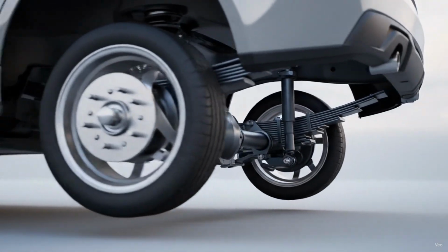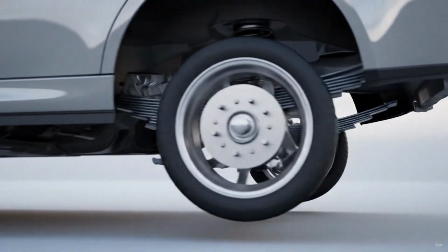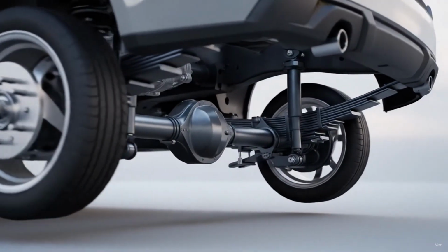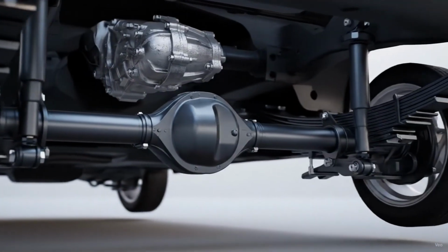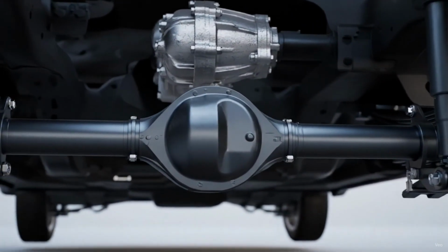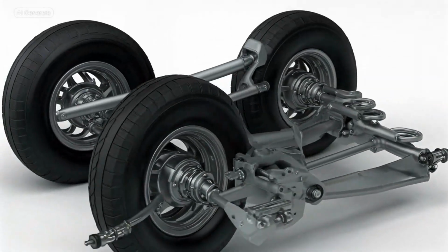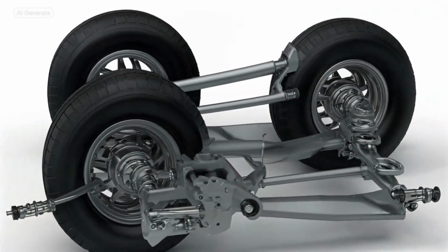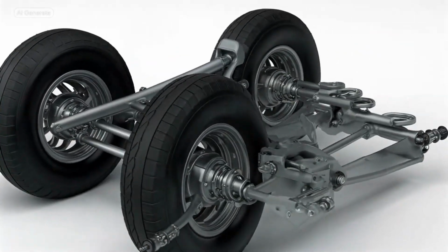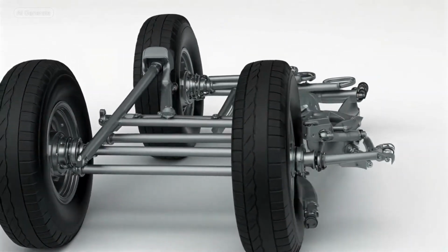They manage the forces, acceleration, braking, and vertical loads transmitted from the wheels to the chassis and ensure the axle remains in its correct position relative to the vehicle body. This specific setup appears to show a four-link system, two upper and two lower control arms, though only lower ones are clearly visible, connecting to the chassis.